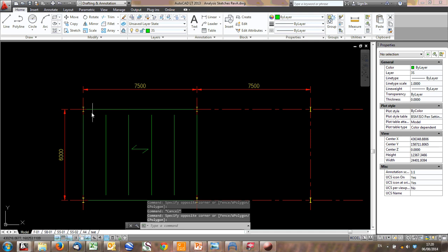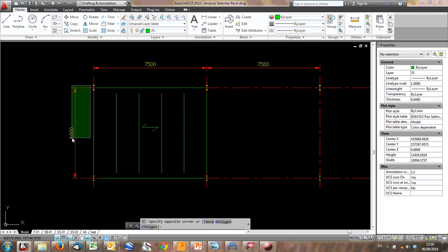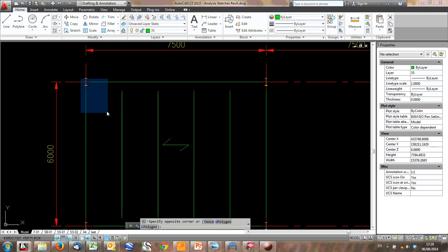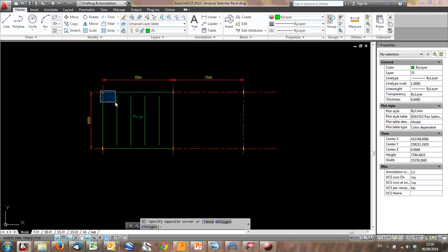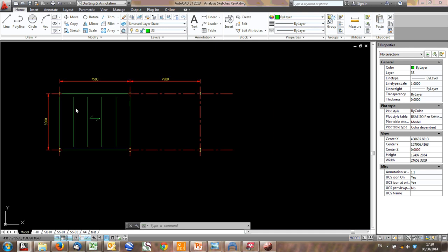And if you want to size that one quickly, this is basically a UDL from here to here. So you can just take the width, which would be 3 meters, halfway between, or if this slab sticks over, it'd be a bit further than 3. You apply it. And that way you can very quickly size floors. And once again, steelwork, you normally size for deflection and check strength. So you can get an idea of what size you're doing.